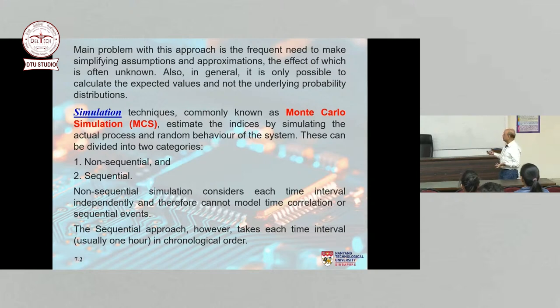However, there are also disadvantages there, because depending upon the technique, and there are two types of simulation techniques, non-sequential and sequential. Non-sequential considers each time interval independently. So that's why it's called non-sequential. There's no sequence. You take every time interval as it is. Whereas in the sequential approach, you take each time interval in a chronological order. Both the techniques exist depending upon the application. One type is more powerful than the other.